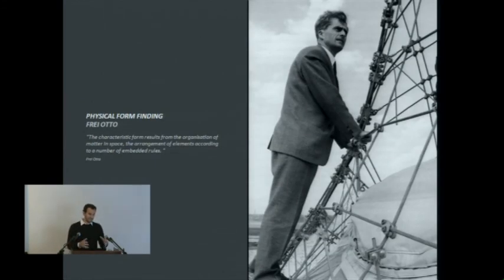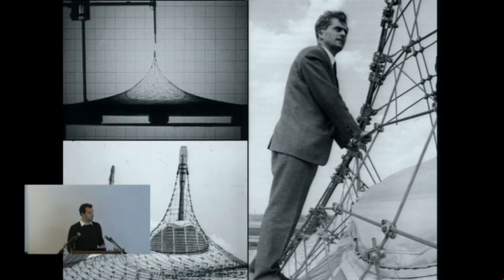On the other hand, I think Frei Otto's quite extensive work and experiments at his institute at the University of Stuttgart that studied what he called form-finding methods may serve as an example of the other end of the spectrum of a material-oriented design approach, because Otto investigated a vast number of different material systems, such as, for example, the seminal soap films and related cable nets that you can see here, in order to study the capacity of material physically computing form as the equilibrium state of internal restraints and external forces.